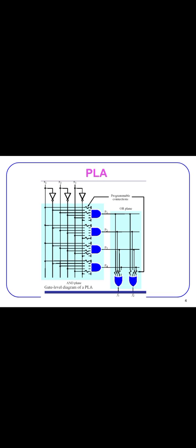The design of this programmable logic array can be done using logic gates like the AND gate, OR gate and NOT gate, by fabricating chips that make every input as well as its complement available to the AND gates, and every AND gate output is connected to every OR gate. Finally, the output of the OR gate generates the output of the chip.